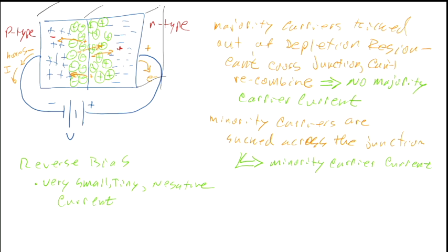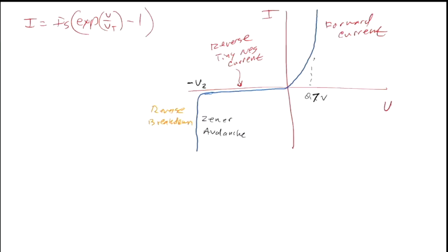And reverse bias condition, where the depletion region gets larger, means that we have a higher voltage on the cathode than we have on the anode. It means we have a higher voltage on the n-type side than on the p-type side, and that chokes off the current, and we only get minority carrier or reverse bias current, which is tiny. And that's these regions. So this region we've got a plus and a minus charge across the diode like that.